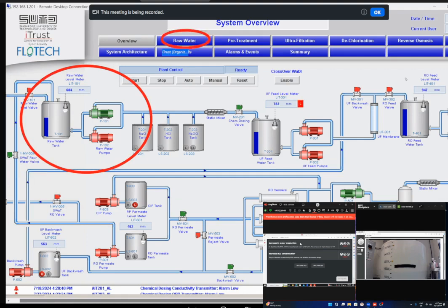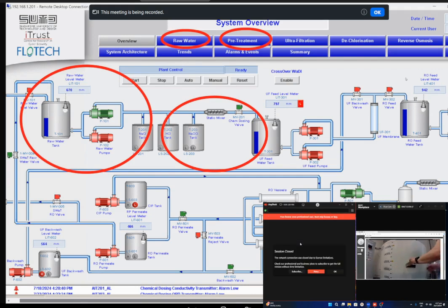The second attack will be on the pre-treatment stage or the chemical dosing stage, which will be on the second stage of the attack among these particular components, which are full of chemicals. So these 2 attacks will comprise the demonstration that is about to follow. Simultaneously, I'll also be pointing to the CCTV feed and also be annotating that. And as you can see, the water level is currently around 900 liters in this stage, as also indicated by the black tape that you see on the screen.